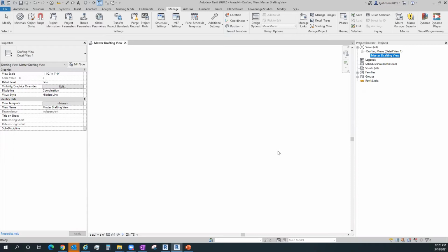So if it is a roof penetration with a piece of duct or a pipe or a vent, and I've got a detail for that, I want everything that's architectural and structural to be halftone, and everything that's my equipment going up through that roof to be black. I was like, that makes a lot of sense because it actually looks a lot like what you're doing in Revit, right?